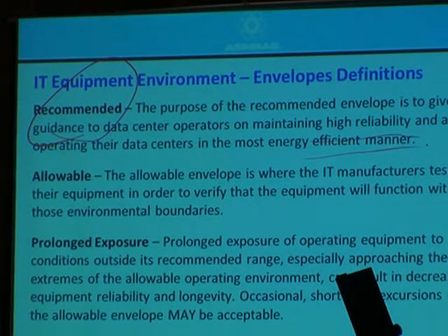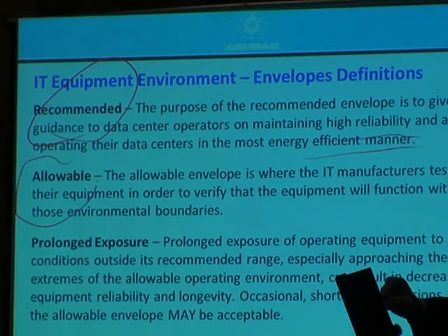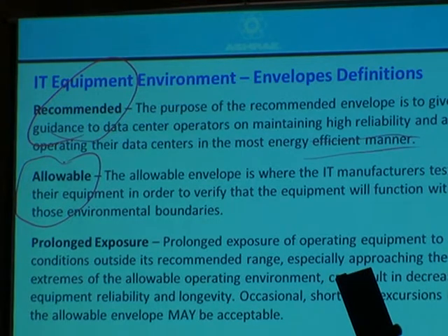Two things: reliability and energy efficiency. That's a smaller envelope, and I'll use the temperature, dry bulb, 18 to 27. However, the IT manufacturers test their equipment to a much bigger envelope, much bigger.